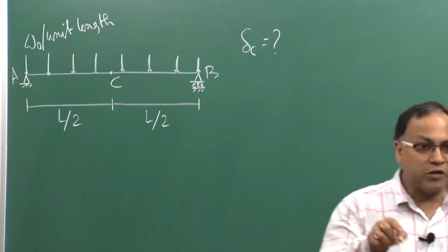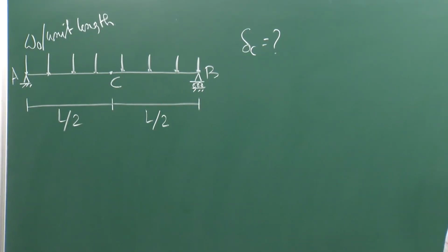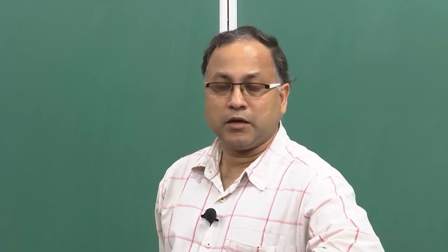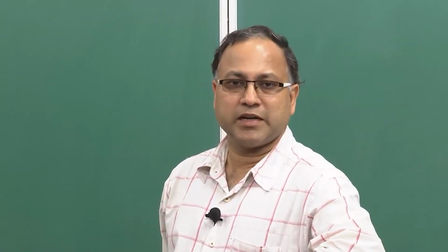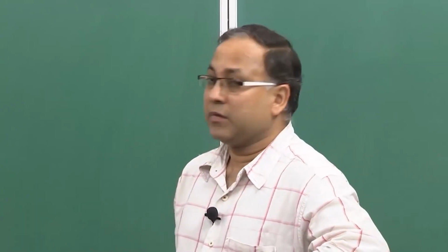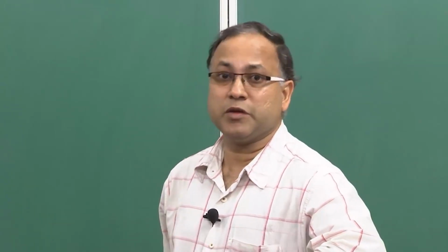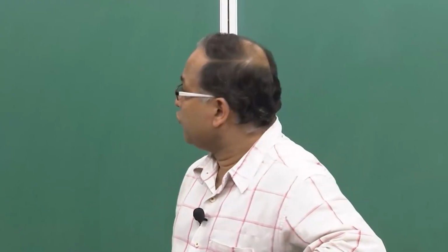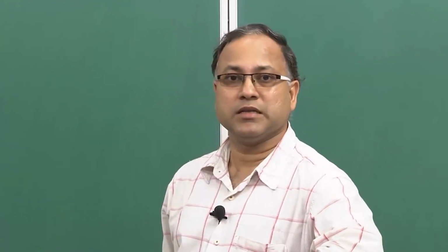But at that central point C, no concentrated force is acting, with respect to which we can take the partial derivative of the strain energy. We know how to find the strain energy for this kind of system, but we cannot take the partial derivative with respect to some force which is not acting at point C.